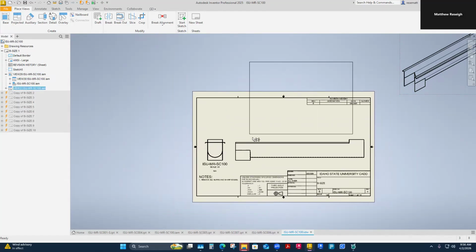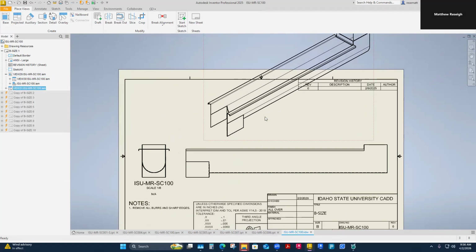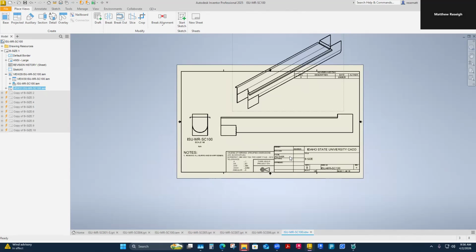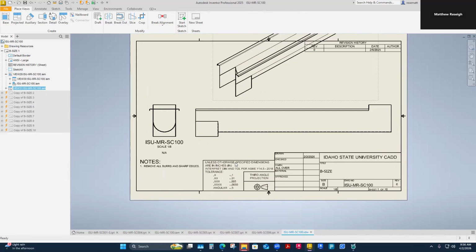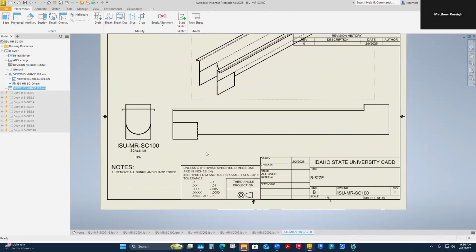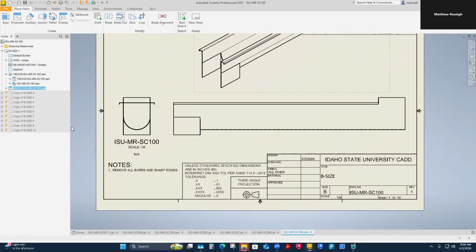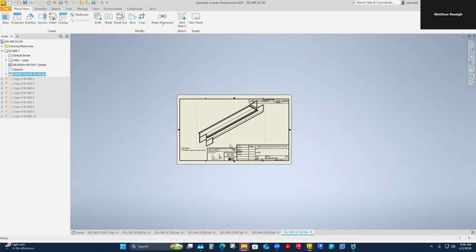And then this is going to grow pretty substantially, to where I might end up eliminating my orthographic views and just keeping a 3D view. In fact, maybe we can plan that actually. I don't think I'm going to do the orthographic views on this first sheet for this assembly. I'm just going to do an isometric view that I can put part descriptions on and call out sub-assemblies. And I think this is going to come down into a second sheet. So I've decided I'm going to delete these two views, and my isometric will be the first sheet of this assembly here.